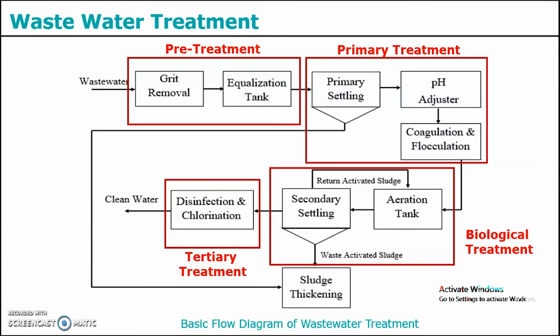The aeration tank is the start of biological treatment. In the aeration tank, colloidal matter and dissolved organic compounds like biological oxygen demand, chemical oxygen demand, and total suspended solids are treated by feeding them to microorganisms.